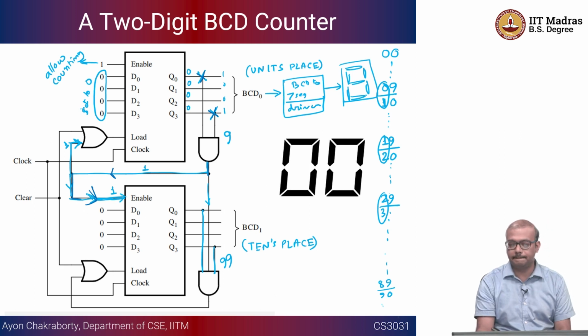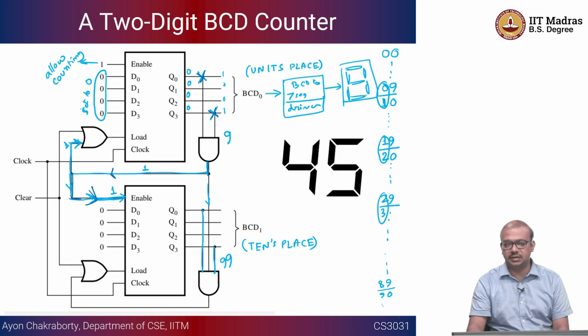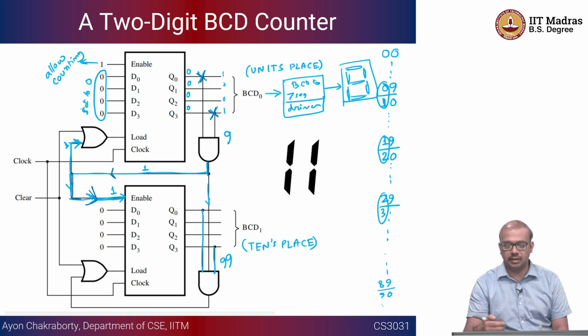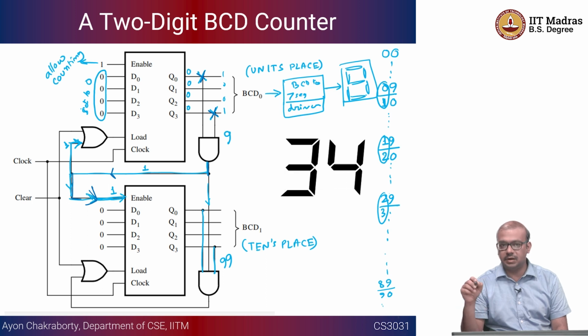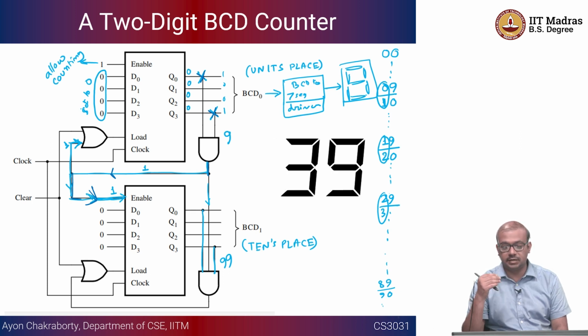the count by 1. Okay, and you can also do a 3-digit number and so on. You can try it out, and it is very easy to verify. You can create a circuit like this and verify this in Circuitverse, right? Circuitverse has 7-segment LED drivers, where you can give the 4-bit number, and you can ask it to show the corresponding hexadecimal pattern. It will show. So it is very easy to verify your design.